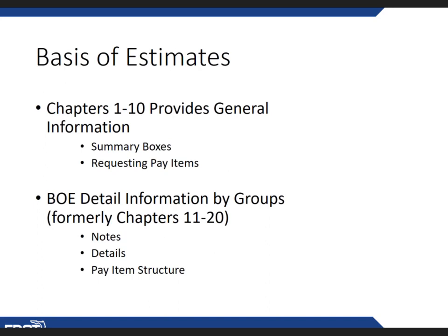Now, if you're looking for pay items starting with a master pay item list, you're looking in the wrong location. So consider starting with the specifications and the associated pay item groups. The specs will tell you exactly what is included in the pay item and what is not. For instance, it might include all widgets or all concrete associated with that particular pay item.